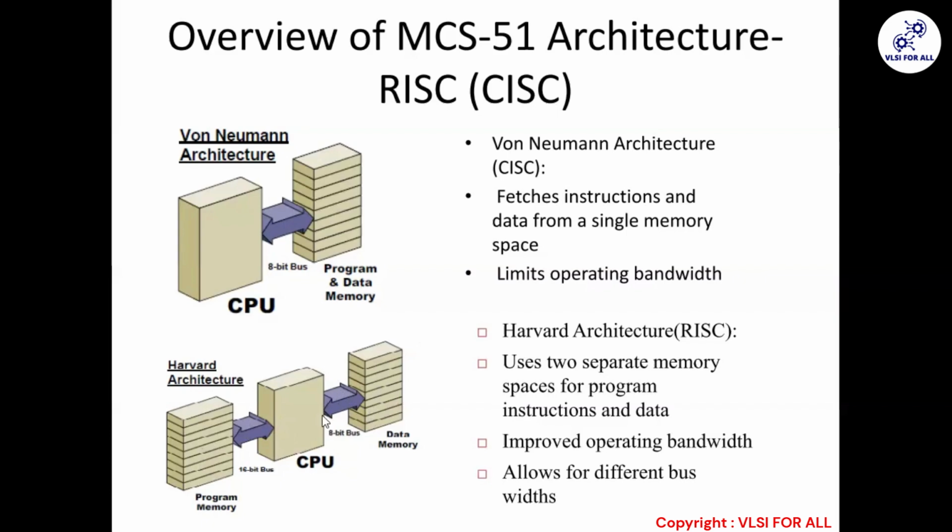So look, in case of 8051, 8-bit bandwidth of data memory is there, whereas 16-bit is for program memory. Means the instructions are of 16-bit, whereas the data which we are fetching is 8-bit, as we know that 8051 is the 8-bit microcontroller. So how many bits of data is it dealing with? 8-bit. So that bandwidth separability is there, and obviously the system is fast compared to the system above.